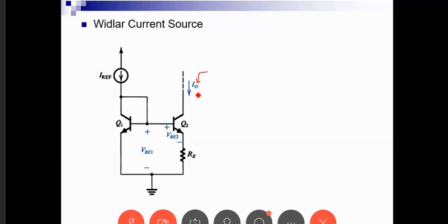We were saying that if I want to size this circuit, even for the BJT, I have to change some area in the device. I want to look at IO relative to I reference. So here they start by telling me, let us start from the fact that those two have a shared VBE. So the first equation tells me that VBE1 is equal to VBE2 plus IE, which flows down here, times RE, meaning plus this voltage.